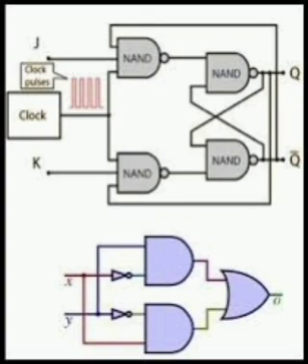Remember, a full adder can be implemented by two half adders and one OR gate. The total number of NAND gates or NOR gates required to implement a full adder is equal to 9. The total number of 2 to 1 mux required to implement a full adder is equal to 7.